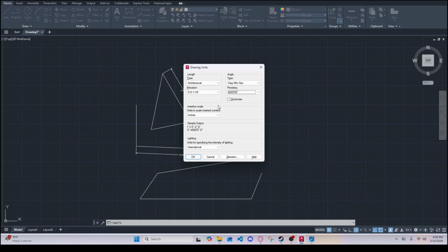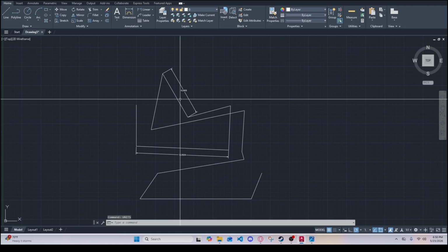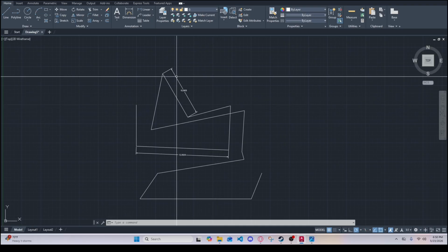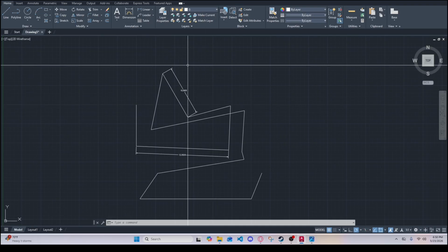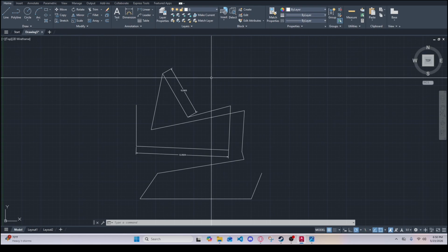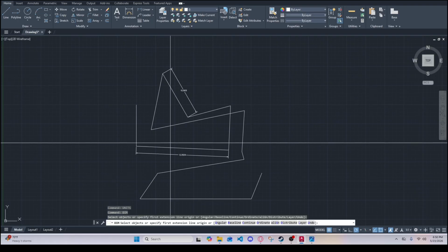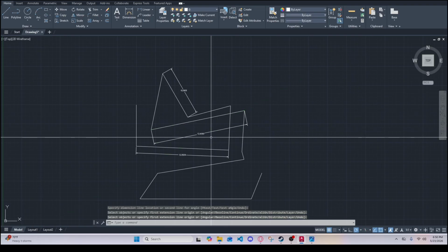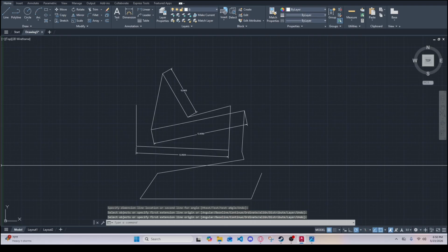Anyways, that's pretty much going to be everything you're going to be doing in this box in your drawing units. You don't have to click anything else. Once you've got everything situated, go ahead and click OK. And you might be wondering, well, how come this hasn't changed? Well, you can either click up here where it says dimension, or you can start typing DIM, and just DIM is more than enough, and it'll prompt you to your dimension command. Now I can click over here and oh, look at that, nothing has changed, and I can tell you exactly why in a bit.